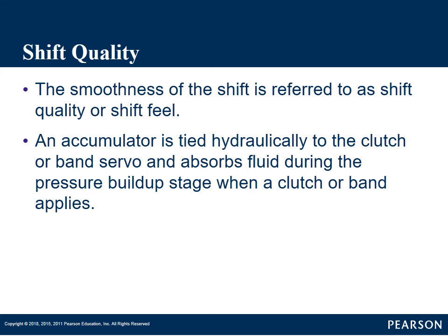We could make a transmission shift really, really soft and smooth to where the customer may not ever feel it, but it shifts too slow and it doesn't apply enough pressure, and it burns those clutches up in our clutch packs and burns our bands up pretty quickly.